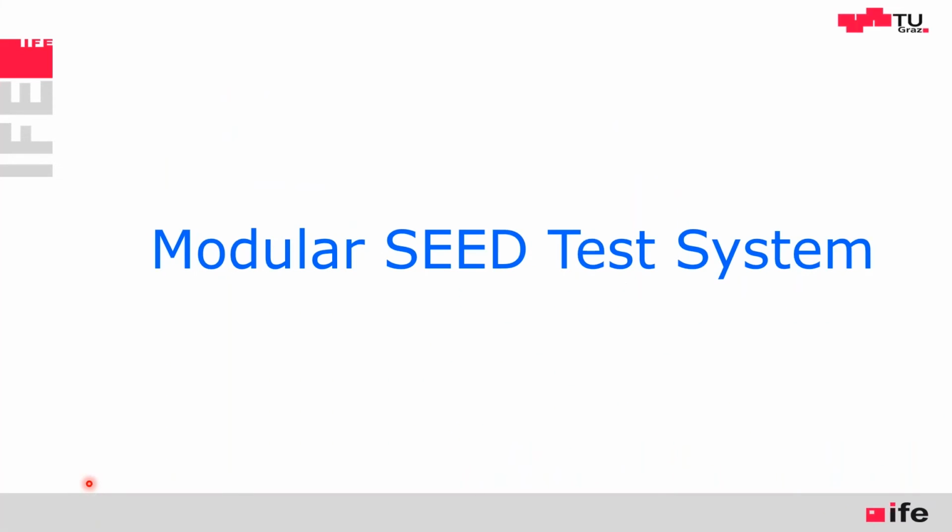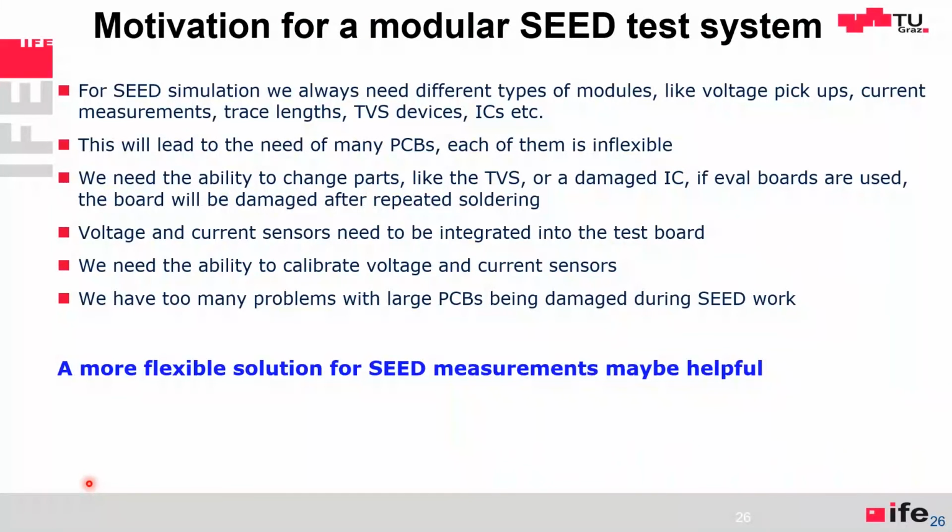How do we get the data? Let's look at that. How do we get these data? We have a modular system, I call that Lego, and that allows us to put ICs on, current measurement, ESD generator, TLP, etc. Because we learned if we take a big evaluation board and we solder 10 times and we blow up an IC and take it out and put a new one in, blow it up again in testing, the board is dead after some time.